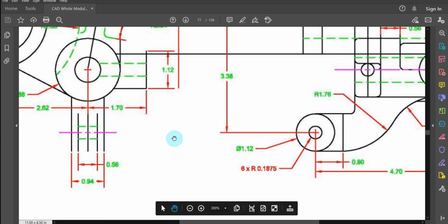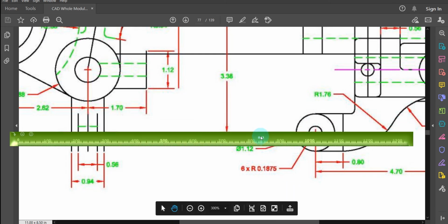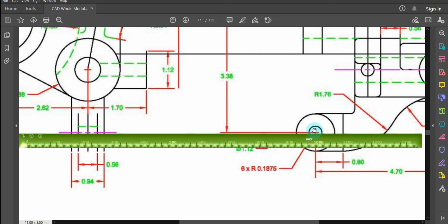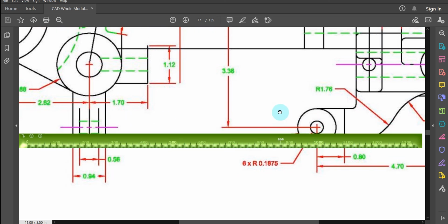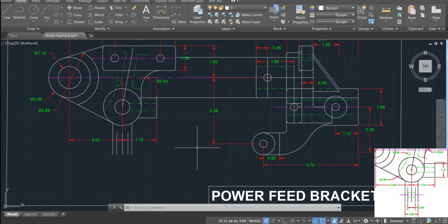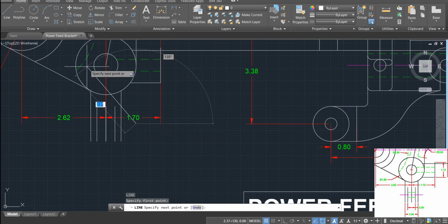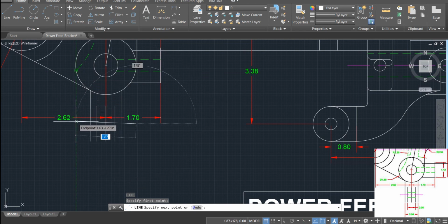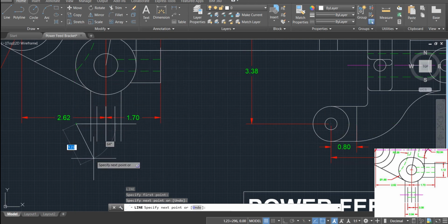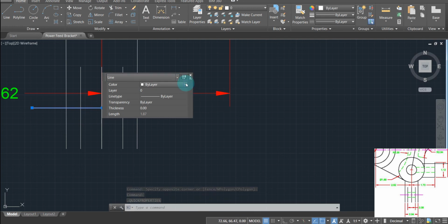Now for the center line here and the two dashed lines, our guide will be the small circle here. So create a line first using the center of this circle for its position and using the side quadrant of this circle here for its length. Then enter and change its properties by double-clicking the lines.